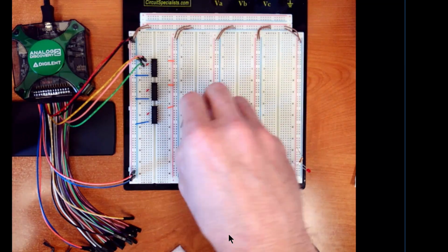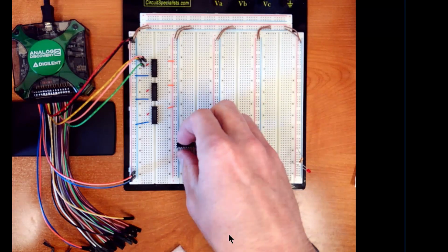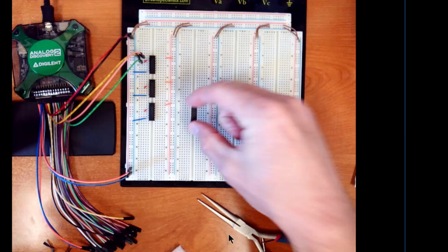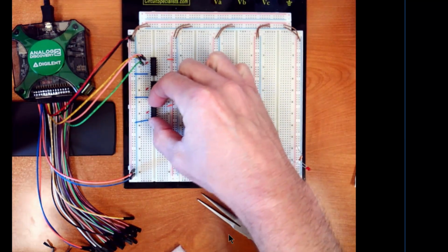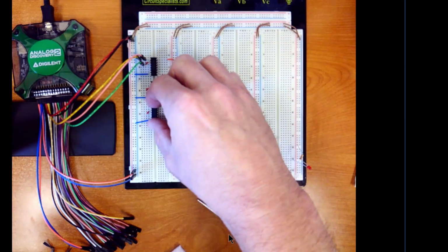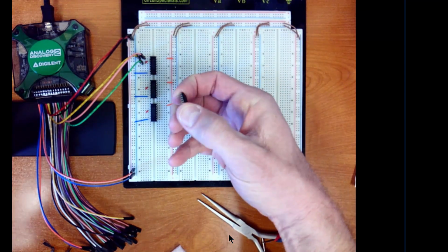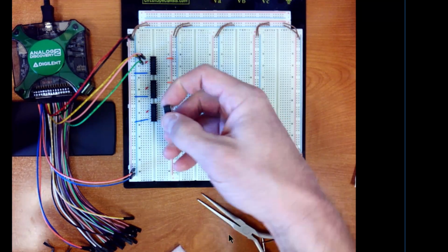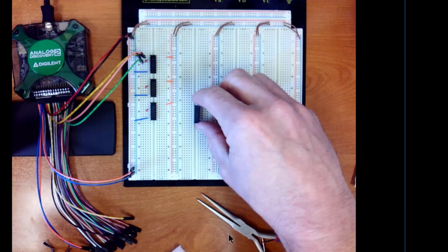Don't do this. Okay, this will save you a lot of pain. Don't come in here and pinch these and try to pull them out, because when you pinch them, it's really hard to grab them, and what happens is you pinch harder and harder and harder. At some point that thing will pop out, and you almost always will squeeze into these leads, and those leads will go into your finger and you'll start bleeding. So never try to take one of these parts out using your fingers.